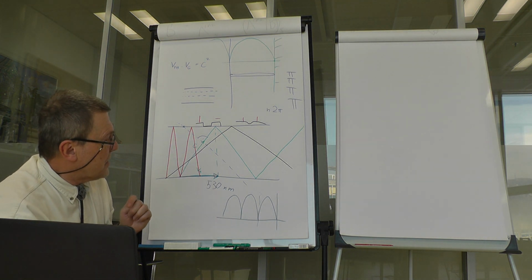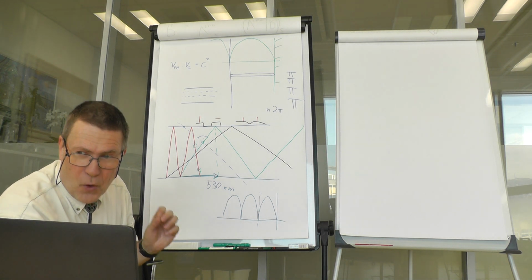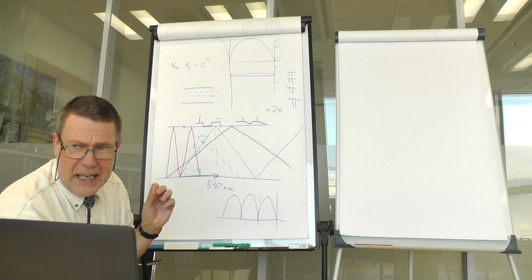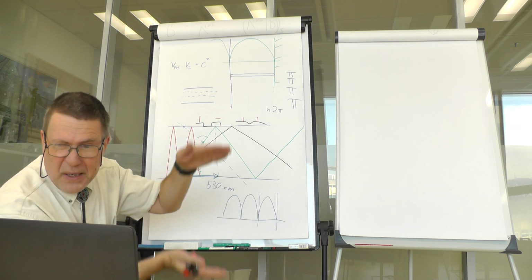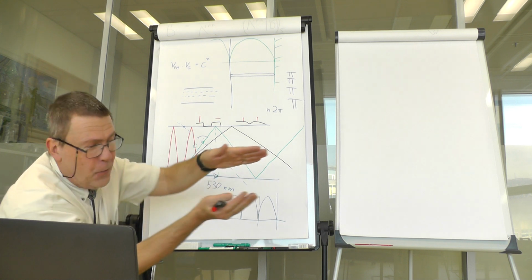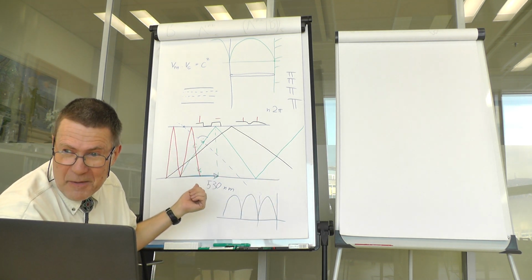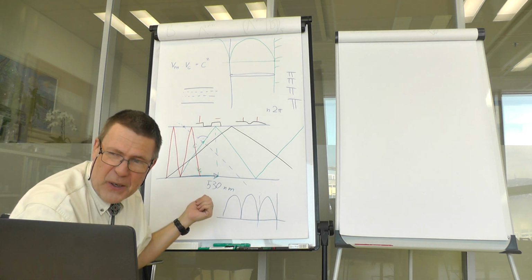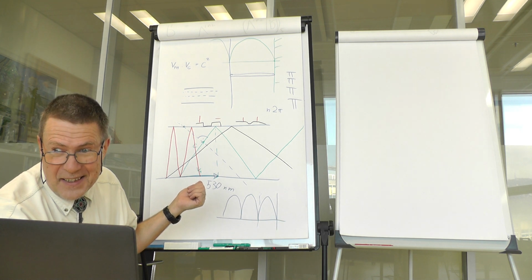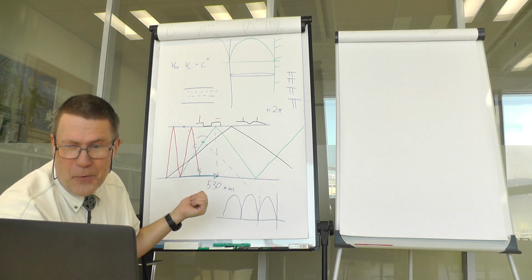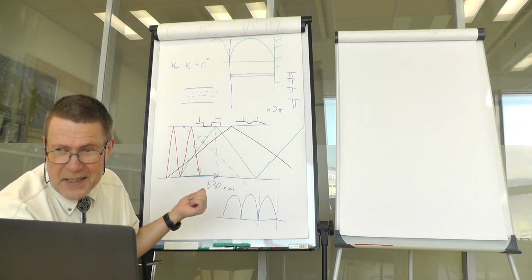And the second point, we have to consider that so far we have been using a monochromatic signal with fixed frequency and just moved the mirrors. But the same effect would be for a fixed set of mirrors with sweeping the frequency, because then higher frequencies would have lower wavelength, and therefore higher frequencies would propagate faster than lower frequencies.